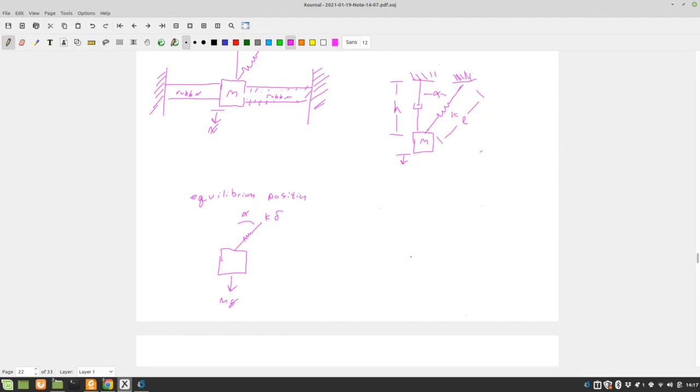And so for our displaced force, we still have mg acting down. But now do we have a vertical force acting up? We have to get our damping in here, because we have to get damping into the equation of motion, so it's got to be in our free body diagrams. So yeah, we're going to have a damping force.